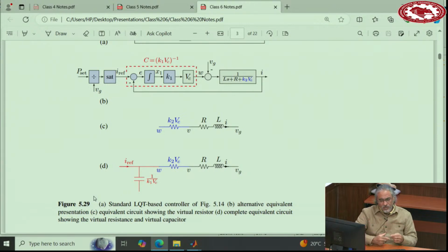This also stores electrostatic energy. So when it is working, it has some energy stored in it. And then when this voltage suddenly drops, let's say because one load switches in, the voltage across this line tends to go down, so the capacitor releases energy.